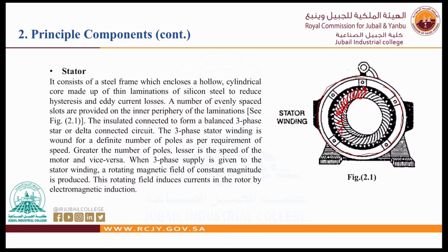Of course, the three-phase windings are separated by 120 degrees, as we know that in a three-phase system one phase is starting from 0, and the other phase is starting from 120 degrees, and the other is starting here from 120 degrees from the second wave. So we will have a three-phase voltage, and we will have a three-phase magnetic field in the stator.